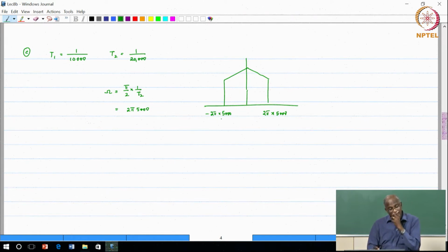Okay. So, again another interesting outcome from this example is that the filtering did happen. The low pass filter actually removed some portion of the spectrum. I passed it to the reconstruction, but because my reconstruction assumes a different sampling rate, my frequency axis is now distorted, and the interpretation comes out saying that, hey, you have frequencies all the way from minus 5000 hertz to plus 5000 hertz. The interpretation is correct, however that was not the intent, because when I passed the signal through, I wanted to remove some portion of the spectrum. So again, keep in mind that the sampling rate plays an important role. Oh, by the way, this will have a scale factor of 1/2.